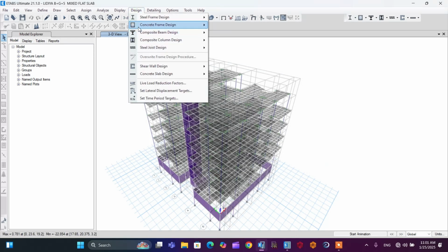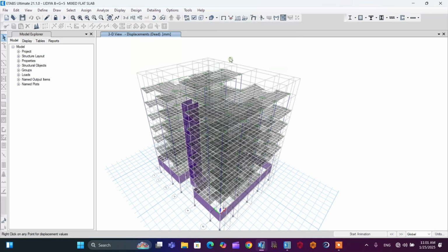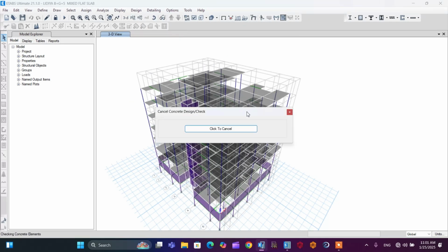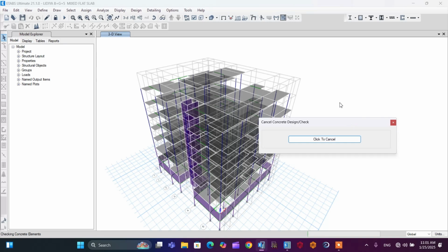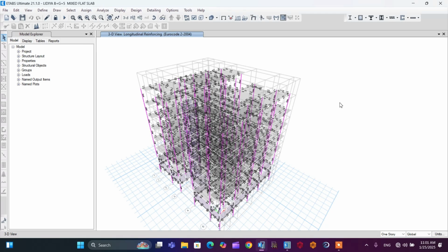After that, you can proceed to start analysis and check. Now the software is going to analyze your frame. It takes some time, so it's better to wait. The horizontal frame is analyzed and it passes to the vertical one. So all the analysis is completed. After this, the software gives me all the reinforcements for the frame and the section sizes.